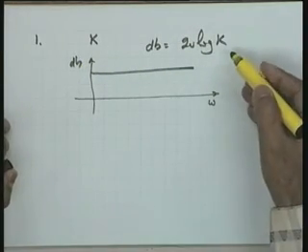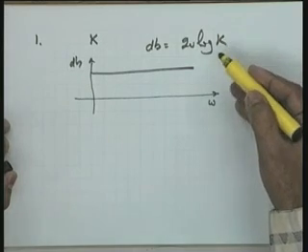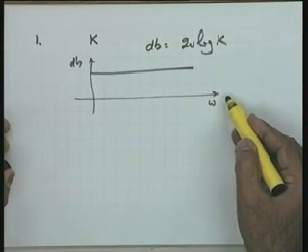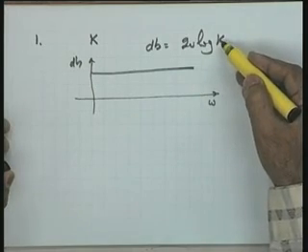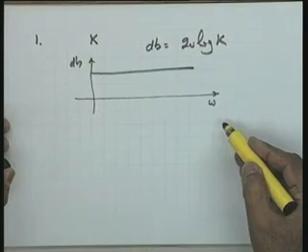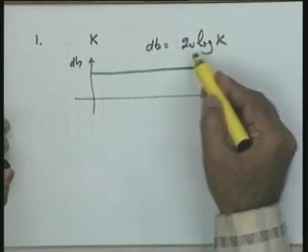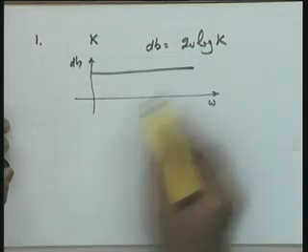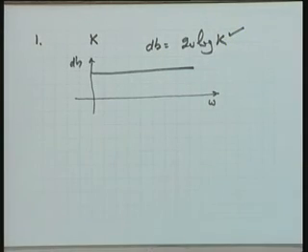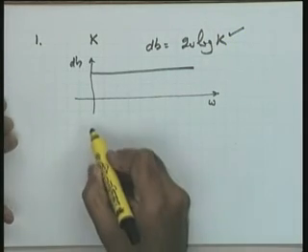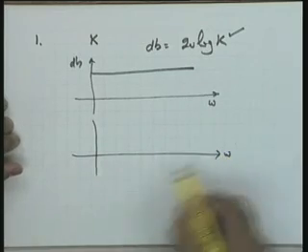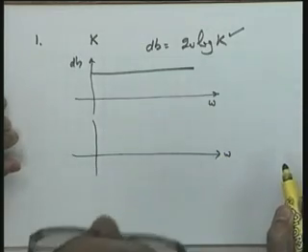You will please note that if your gain k is greater than 1, this line will come above this particular axis which you have taken. If it is less than 1, dB will become negative and your line will come below. So dB is 20 log k. So the line coming here or here will depend upon the magnitude of k relative to unity. Phase angle, well, it remains. What is the phase angle in this particular case? 0. So 0 degrees phase angle will come.